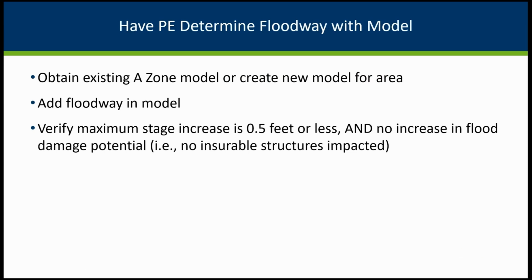So this still goes hand in hand with the previous slide, as far as if there's a proposed development of 50 lots or 5 acres, like Ceil had shown in that slide, the federal requirements do require that it be a detailed study, or at least a detailed methods study, even if the final map change remains a zone A. So to do a detailed study method, you do have to determine a floodway.